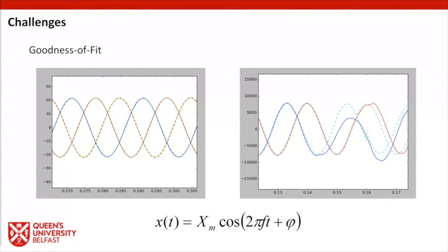The magnitude of our blue signal has become suppressed, and a DC offset has occurred, and one would say there's probably even a phase step. So this is really a perfect storm, as far as a phasor measurement unit is concerned, of an unsolvable problem. As a result, our phasor estimator has tried, with the degrees of freedom available to it, to solve for this, but it can't.